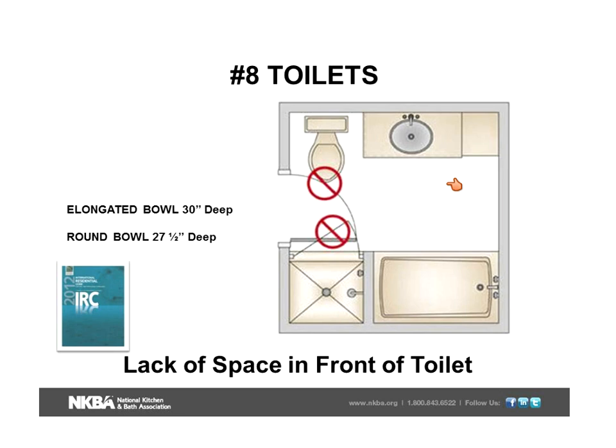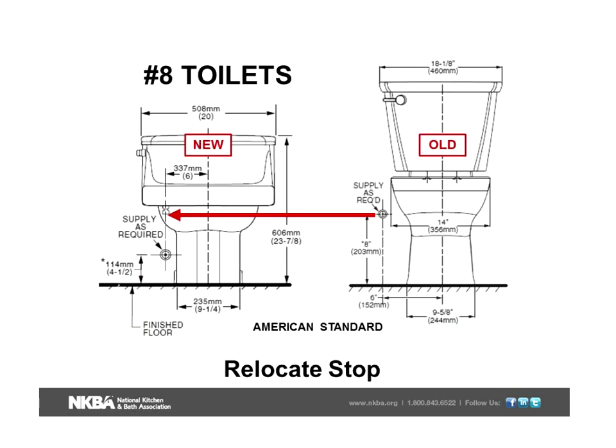It happens a lot. We failed to measure the door clearance on that existing round 27.5-inch deep bowl or toilet. We put an elongated toilet in, the door will not close. It's 10 o'clock at night when the homeowner finds out. They're not real happy because you didn't mention this. Another mistake made by the do-it-yourselfer, but we make that mistake too, is kitchen and bath designers. So make sure that the door will open. That is a code issue.